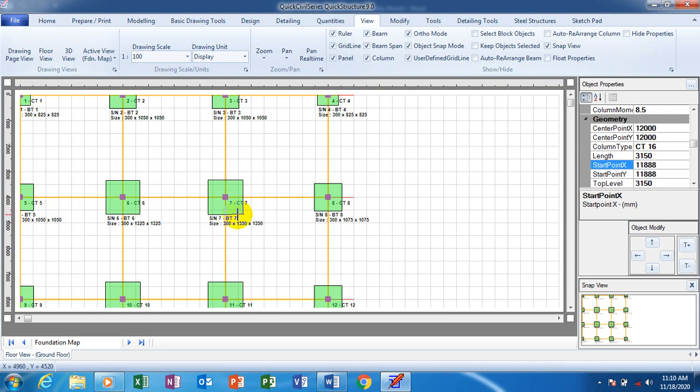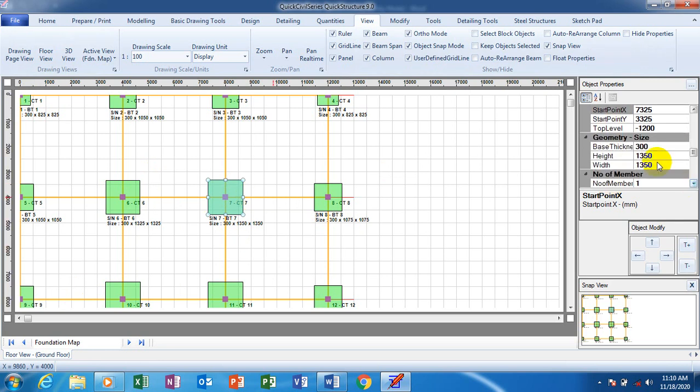Okay, you are at liberty to make adjustments to any of these bases that are here. I'm showing you a match property on this software. Let's just say I make this 1400, for example, and I want all these columns in the middle to be 1400. I'm just citing an example, but ordinarily I can just leave it as it is, for practical purposes.